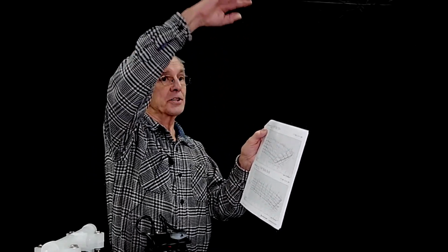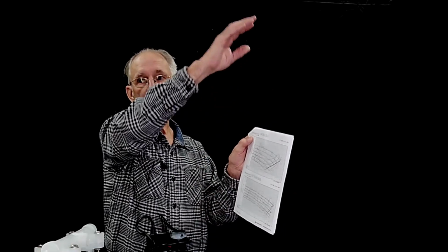This curve is up at 200 feet. And this curve is at 50 feet. But those other curves are just above this. So changing the speed essentially moves the curves up and down on the chart. Now, there's a couple of other lines that are real important. You see these lines here, the dotted lines or dashed lines. Those are the horsepower curves.